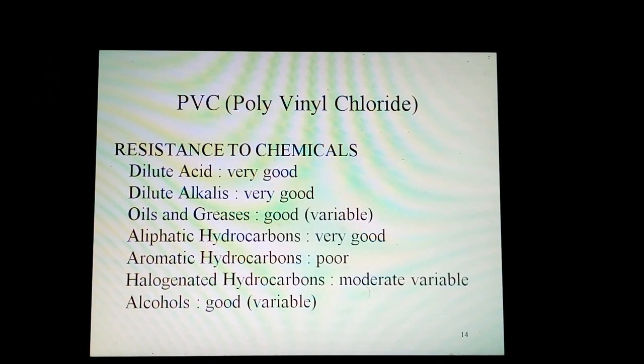Resistance to chemicals. With dilute acid it is very good. With dilute alkalis it is very good. With oils and greases it is good or variable. With aliphatic hydrocarbons it is very good. With aromatic hydrocarbons it is poor. With halogenated hydrocarbons it is moderate variable. With some alcohols it is good.